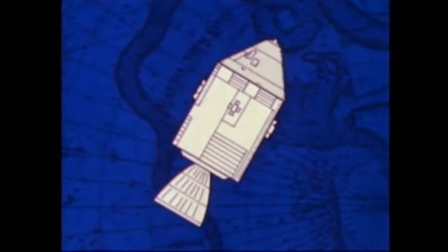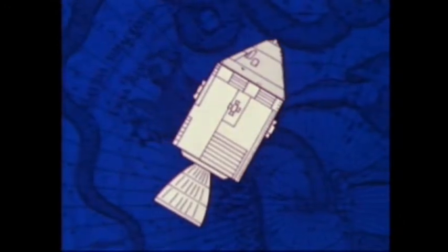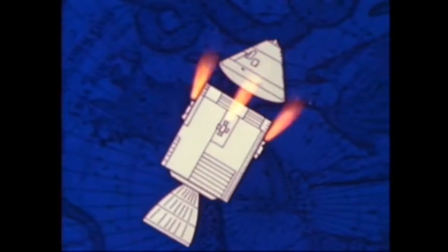Before actually entering the atmosphere, the service module, which contains the primary propulsion system and all but a very limited oxygen and power supply, will be jettisoned. This is roughly analogous to a scuba diver taking off his air tanks before starting up from the bottom of the sea and holding his breath all the way to the surface. Once the command module enters the atmosphere, it has about 1,000 miles and a bit over 2½ minutes of controllability divided into 2 brief control periods. Most of this controllability will be used up during the first control period.